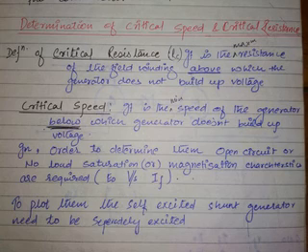Now you want this characteristic. How can you do it? Think about that. Within 10 seconds, you can do nothing to the machine. You start it and the generator is readily available. Now what you require is different IFs and the corresponding voltage. How to do this? The only option is you have to separately excite the shunt generator.